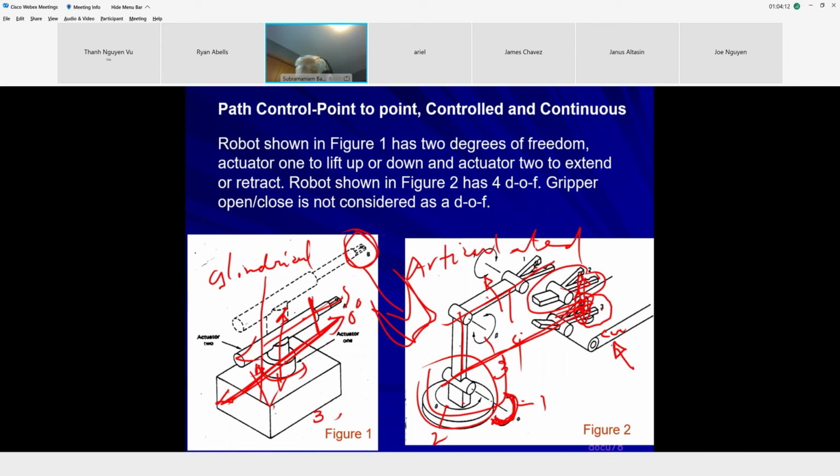It does the same job, but it does it with a bit more involvement of the different degrees of freedom, more programming involved. The advantage of this machine over this machine on this application is that this is more involved, more expensive. This is cheaper, but this has no capability if, let's say, this part changes to a tall milk carton that we are going to handle. That means you have to adjust this position of pickup. A lot easier on this machine. Here more adjustments are required.